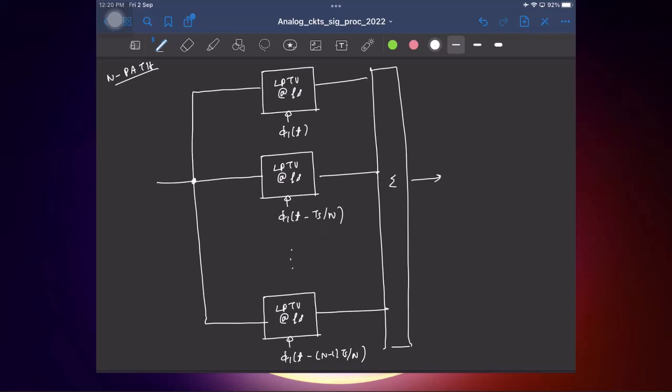And again, if you feed a sinusoid at a frequency f, you will have tones at f plus k times n fs, and vice versa. What frequency components can fall back to f plus k times n fs? Only frequencies at these values can fold back to a frequency f at the output. Is it clear?